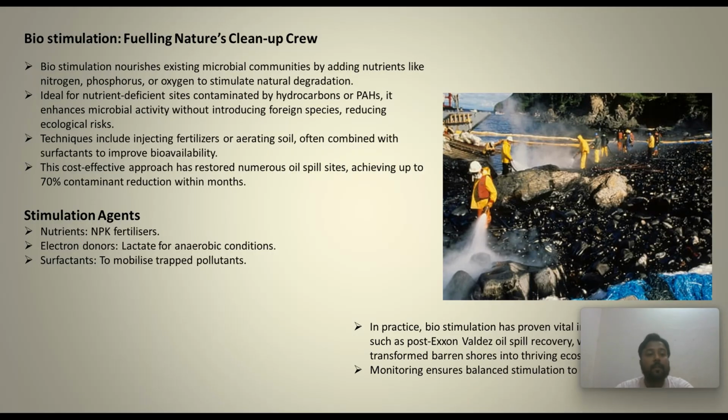It enhances microbial activity without introducing foreign species, reducing ecological risk. Some of the techniques under biostimulation are injecting fertilizer or aerating soils, often combined with surfactant to improve bioavailability. This cost-effective approach has restored numerous soil spill sites, achieving up to 70% contaminant reduction within months.